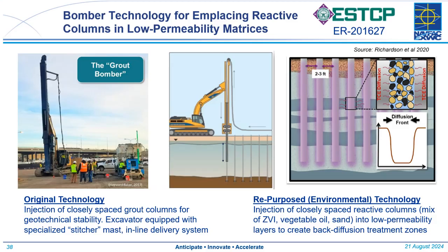What you see is an excavator equipped with a specialized stitcher mast, and this is a tool deemed the grout bomber, which was used for fast inline delivery of grout columns to stabilize shallow, geotechnically unstable soils. And the graphic in the middle, cartoon in the middle, sort of illustrates that.